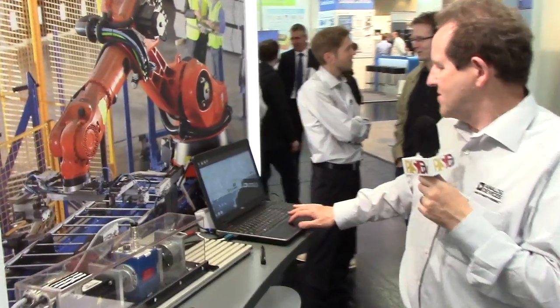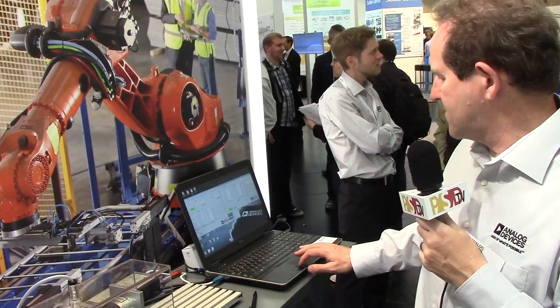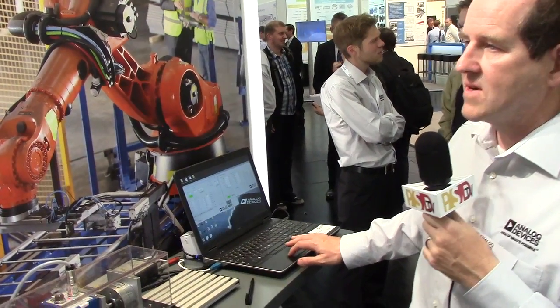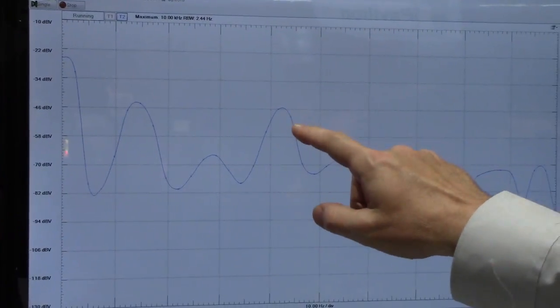And in this configuration you have 3-phase current measurements, which happens to be very good at self-correcting for offset drift. Very commonly you'll just use 2 current measurements. Now in that situation the offsets don't cancel because you're measuring 2 currents and it's a common mode signal. So if I get rid of the 3rd current signal here, I'm going to do that in software, I introduce this major ripple component.